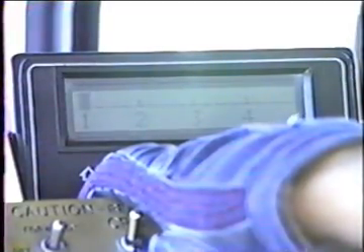Right now it's blinking on the number 1 nozzle size. We're not traveling, we're at 0 ground speed, so it says for this ground speed we should have the smallest possible nozzle in the spray bar. That's not even right information. We should have plugged up nozzles for 0 ground speed.